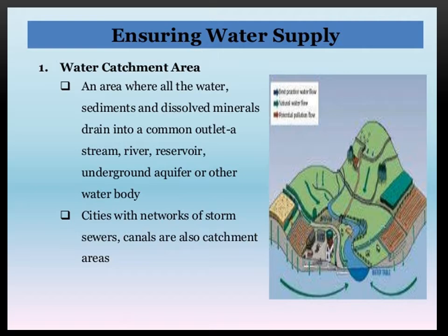The type of land use, farming or urban development, and the associated activities have a direct impact on the water quality of the catchment. For example, the clearing of trees will result in a greater amount of sediments in the river system. So that will actually affect the quality of the water, that will contaminate the water and will reduce the capacity of the catchment area.